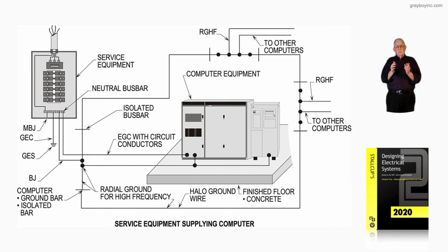Now the feeder, as you see there, is designed by 215.2(A)(1)(a), the conductors. The overcurrent device is selected from 215.3, and everything is listed, labeled, and approved in accordance with 110.3(B) and (C) of the code. Now, these are the most important sections related to 250.96(B) when you're hardwiring. Now, there are other call-outs that you see for a disconnecting means, ventilation, light switch, and those kind of things.